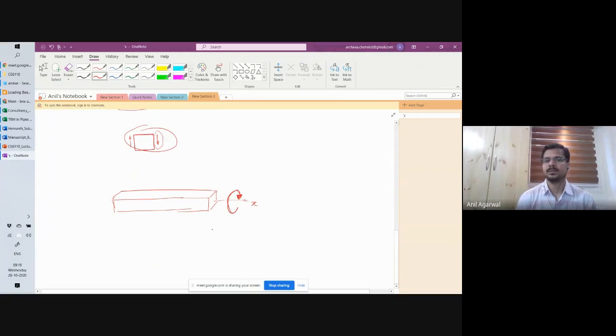Okay, you can call it x-axis. So moment about x-axis. Okay, but if I have moment like this, and then also at the same time a moment acting this way, which is opposite of this moment, in that case you will have a torque. Okay, and then you can give it a sign convention. In one case you are twisting it this way. So in this way, if you can imagine, this twisting is going to be like that. Okay, so this you can call positive. The other one would be negative. I'm not drawing it again, but you get the idea. So twisting in the other direction will be negative automatically. Okay.